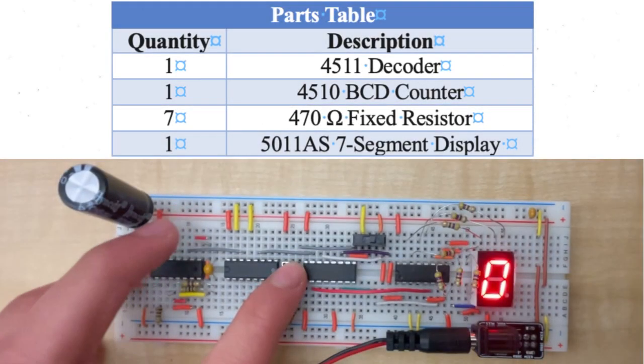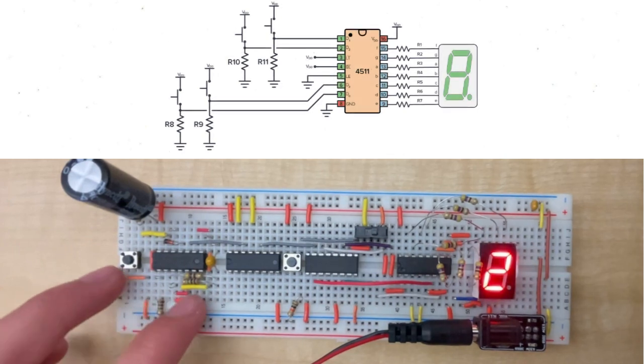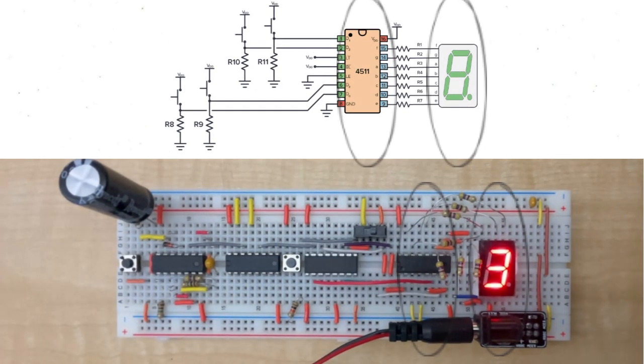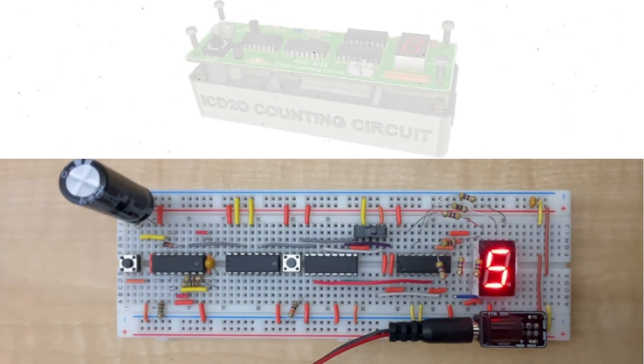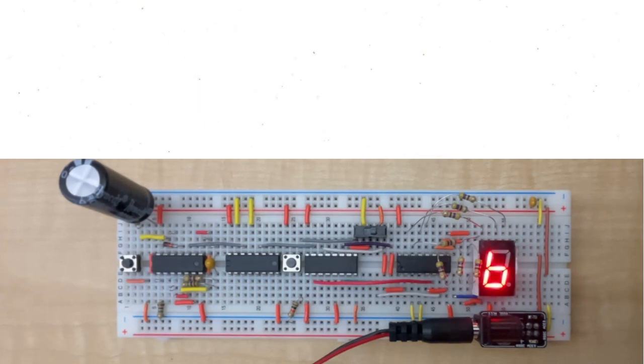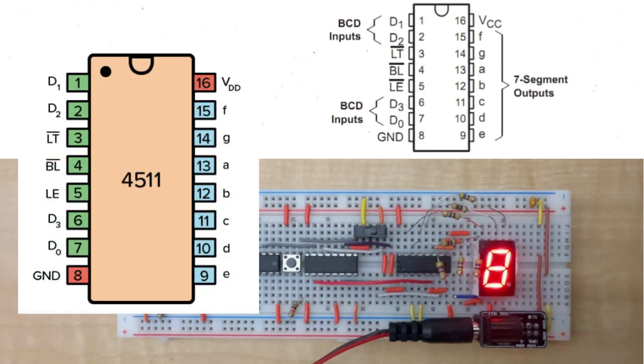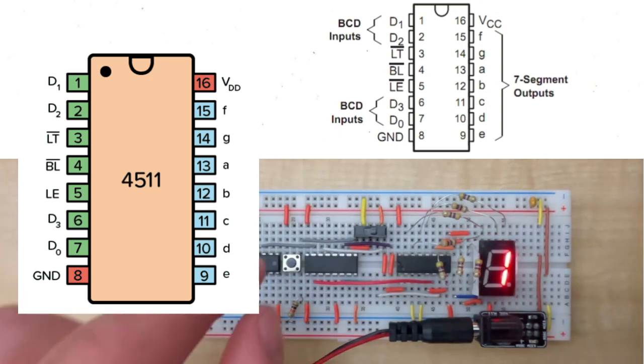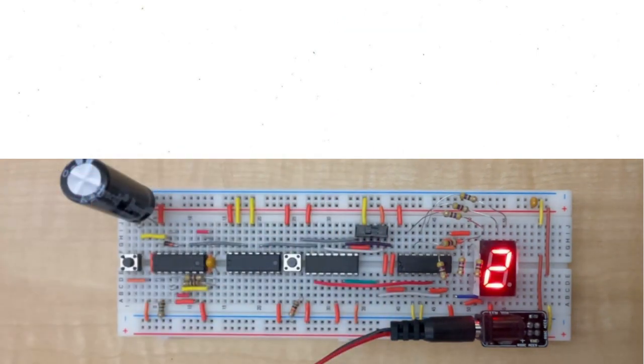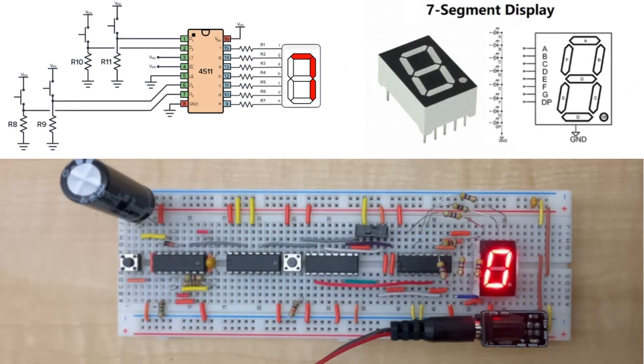Parts E and F, Binary Counting Decimal Decoder, and 7-segment display. This circuit consists of 4 additional parts. This circuit is broken up into 2 subsections but ends up as one circuit, serving as the prototype for the final counting circuit. The 4511 internally processes BCD input data, decoding each signal combination to decide which segments of the 7-segment display should be lit to represent the right number. In the output phase, the 4511 produces signals that correspond to the 7-segment display segments, allowing decimal numbers to be displayed. By carefully activating combinations of segments, the chip organizes the display, showing the correct number.